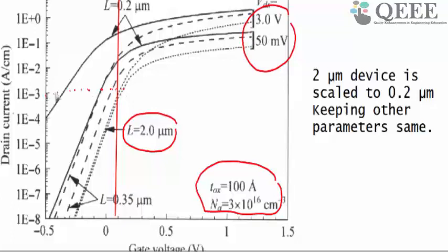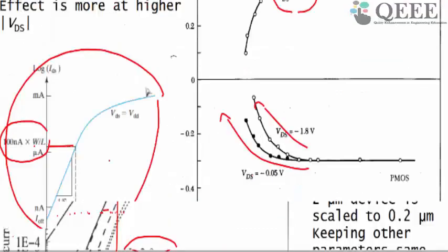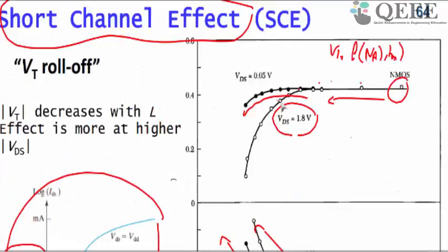If you measure the threshold voltage using some constant current method, suppose I assume the current is here, you get a threshold voltage that is not very different between the linear mode and the saturation mode. These are for two different drain biases, one for the linear mode and the other for saturation mode. For very long devices there is not much difference. It may be around 20 millivolt or 10 millivolt, and you won't see that clearly in this plot.